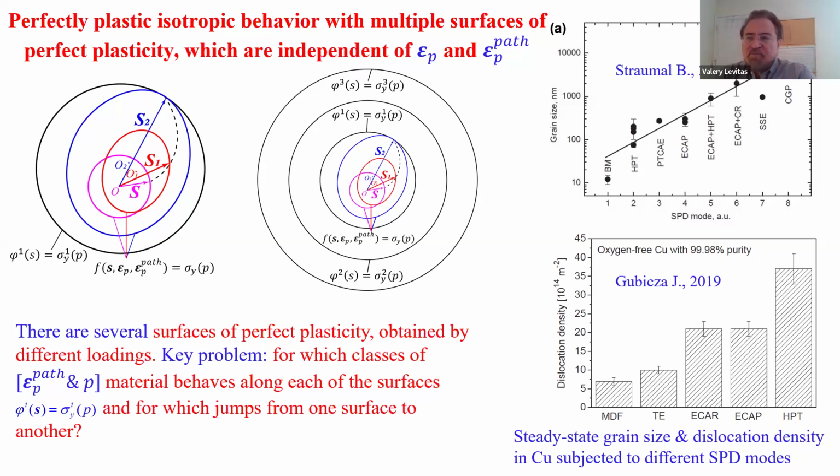Because what happens is that this was an ideal single crystal, and the lattice loses its stability. So shear stress reaches the instability limit, and then the material just goes where it can go. Actually, it goes to melt at room temperature. Shear stresses drop to 0. Then from melt, it goes to amorphous solid, so shear resistance is reinstated.